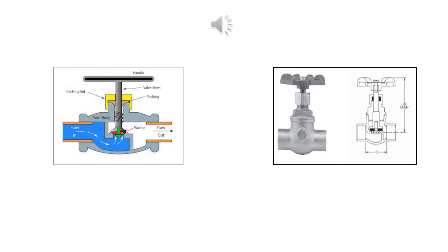For applications with high temperature steam service, globe valves are installed so that the pressure is above the disc. Otherwise, the stem will contract upon cooling and tend to lift the disc off the seat.